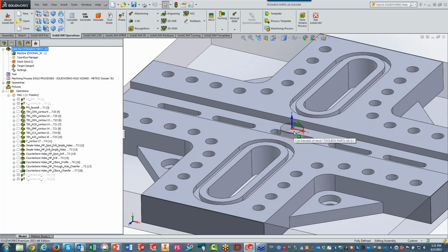Now, if I were to do this by probe, and without the use of SolidCAM Solid Probe option, you would have to go, every single time you put a part on the machine, up to the part physically and put your probe on, check it, and have it update your home position. And God forbid you make a mistake.